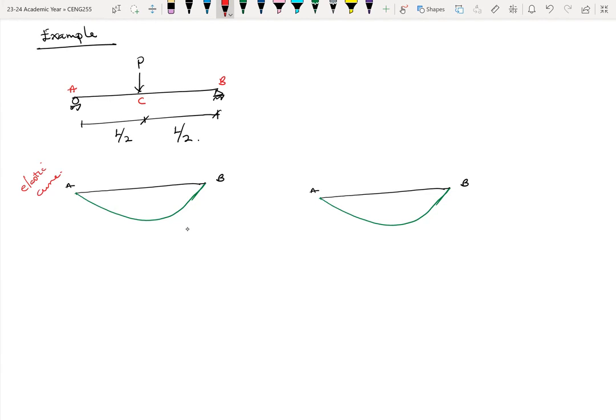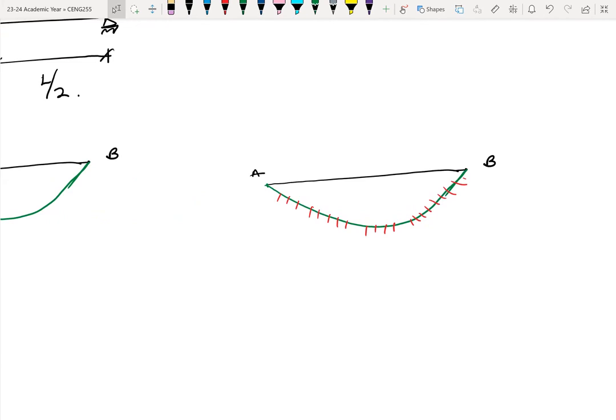All right. So when you look at the elastic curve, let's say we have different points on the elastic curve which are important to us. Okay, so all these points, we can find the tangents to these points. Let me just exaggerate a little bit. So we can have tangents passing through as many points as possible. And as we keep drawing the tangents, you would realize something interesting. At some point, one of the tangents is horizontal. At some point along the elastic curve, one of the tangents would end up being a horizontal line.